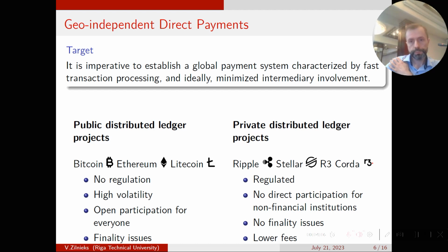So the goal of our work is an optimization of a climatic curve, not in real time, but for the city of Salerno. The baseline was considered the climatic data in the winter season 2020-21, and the baseline temperature control strategy defines the water supply temperature as a linear function of the external one. Of course, considering the inertia, there are some problems for few hours, because we can change the shape of the climatic curve with a parabolic one.